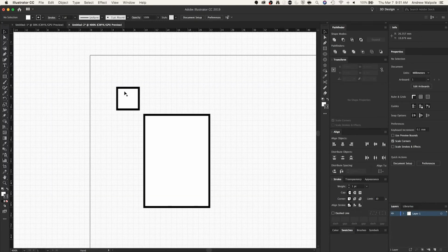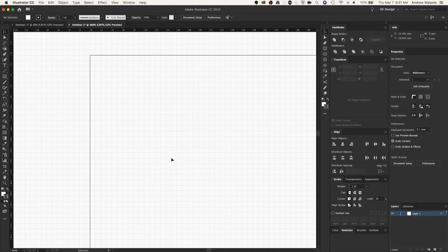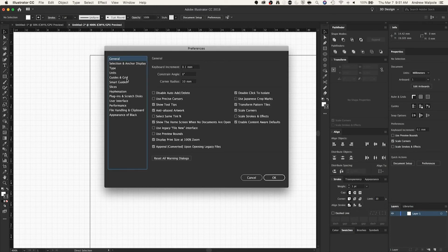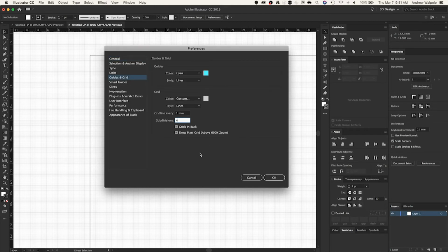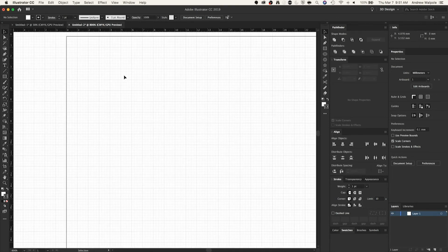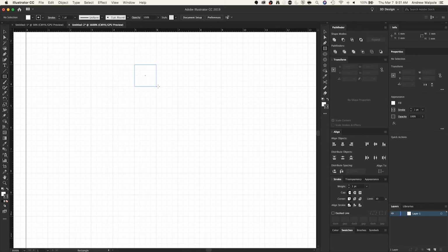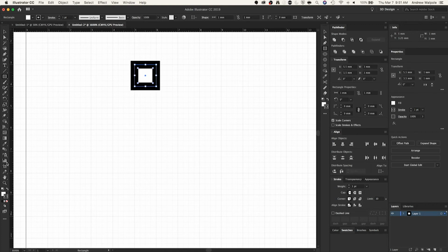And really just setting up your grid in a way that works for you. So again, if you wanted 0.25 increments, so like 1/4 millimeter increments, we can go back to that grid definition. We can change this to subdivisions 4, right? And we can zoom in here, and again, every time I go to one of these smaller squares, it's going to only increment by 0.25. So we have a lot of ability to control the precision with which we're drawing.